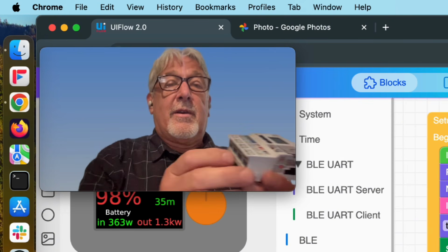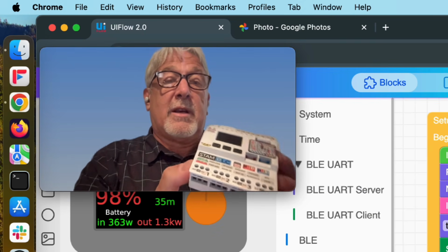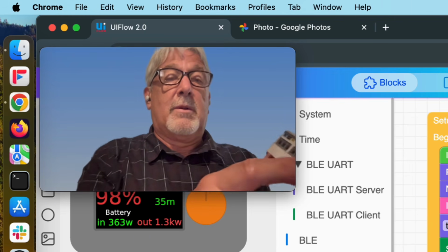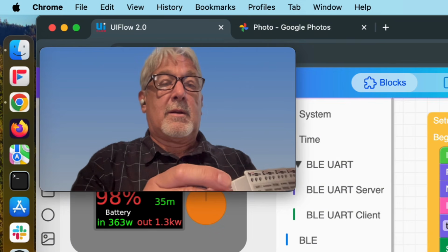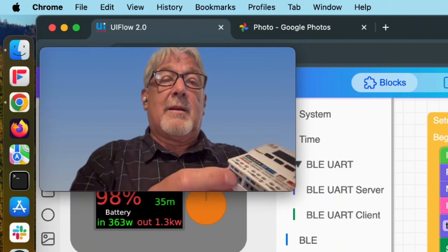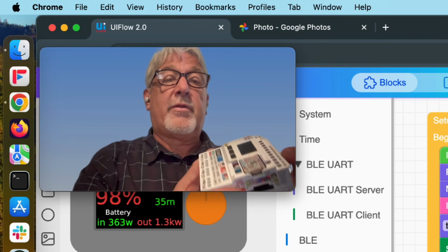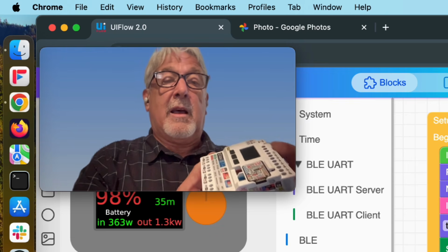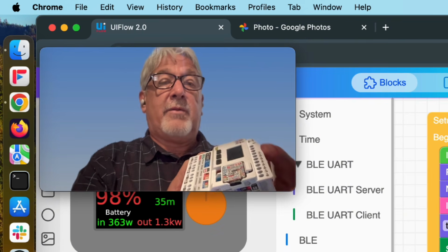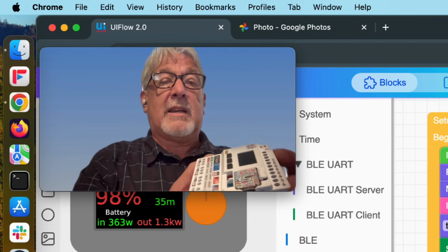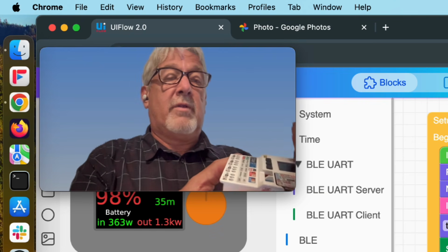I've also got this, which is a programmable logic controller. It's about £45, and it has multiple relays, up to 10 amps. So it has 4 relays. It has 8 inputs for voltages, so it can detect between 6 and 36 volts. So I can detect if any of my circuits are powered, and it has buttons and a screen.